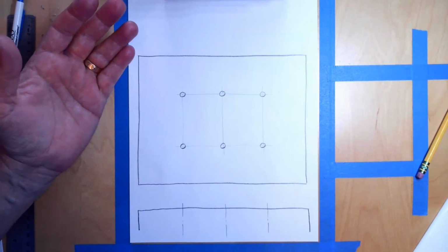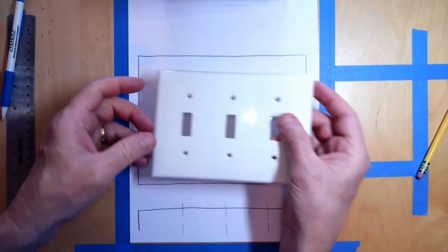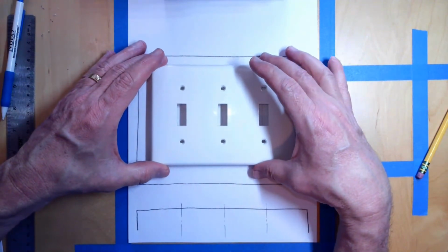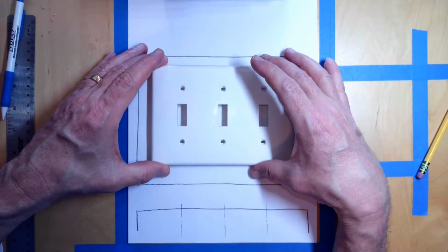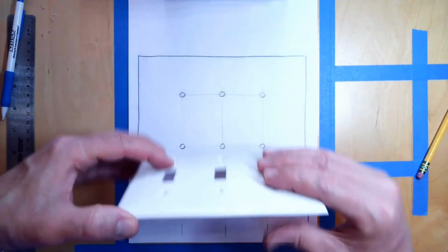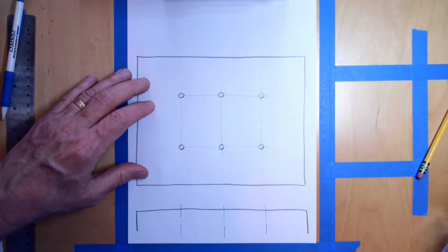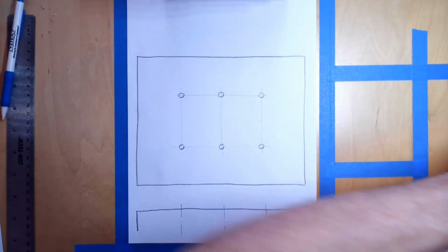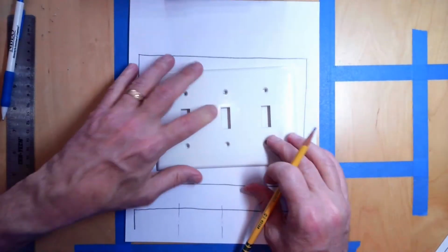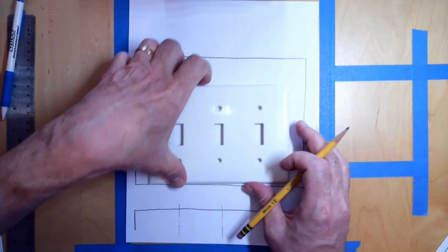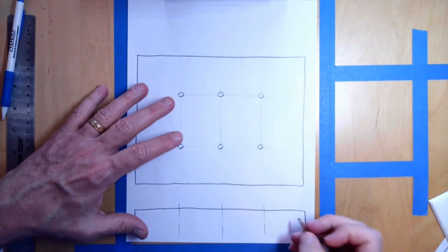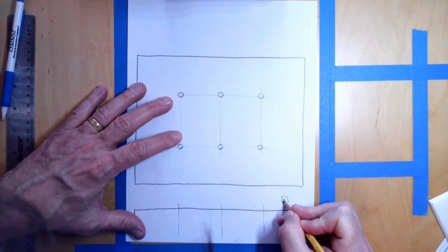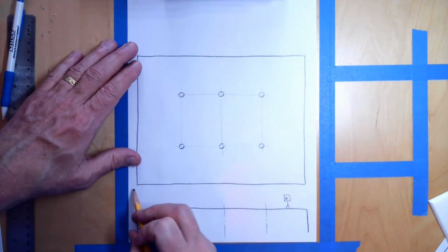So that's a perfect situation for composite positional tolerance. All right. Now, let's go ahead and figure our datum reference frame. The primary datum is going to be the top surface here, the surface of the box, because I want the cover plate to attach flat.